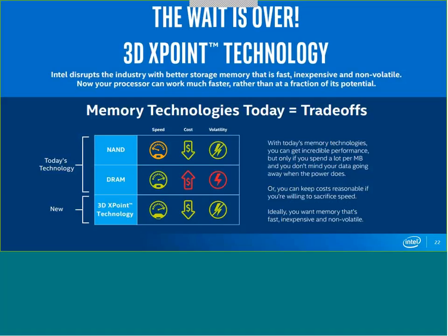Single-level cell only goes so deep in density. Single-level cell is by far the best and the fastest. It can last a long time, but it just can't scale in capacity. So Intel standardized around MLC, and other competitors use tri-level cell and so on. So right now, we have our NAND drives, what I just read to you.